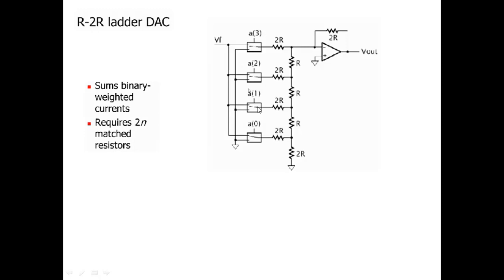So now we see that only the top and the bottom branches are being shorted. Why? Because the inputs for A0 and A3 are both 1. Hence we have a shorting of the first and the last branch, and we have an open circuit in A1 and A2. So the middle rows are open circuited, and the bottom and top rows are short circuited. This is how the voltage level will be changing.